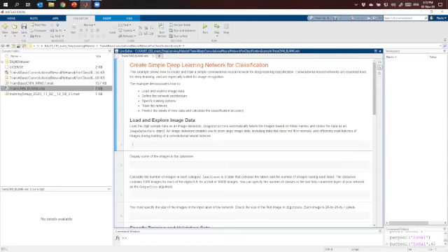So let's start to explore the data. To load the data, you're going to use the function imageDatastore. Let's give the name MNIST, and I'm going to use the imageDatastore function. When you type in this live script, it gives you the function suggestions. If you press Tab, it's going to complete the function. I encourage you to use this.